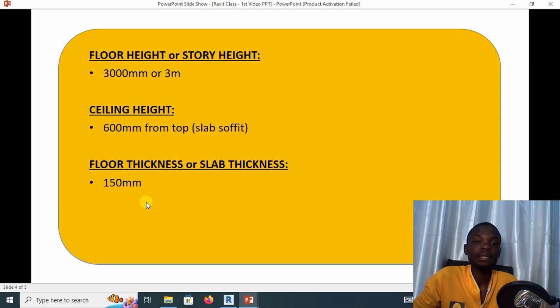However, if you are designing maybe factories or church halls or mosque halls or malls or commercial areas where they are expected to be crowded, your height should be more than 3 meters. Standard height of commercial buildings, standard floor height of commercial buildings should be at least 4 meters, 4.5 meters, or 5 meters, as the case may be. But a residential building standard is 3 meters.